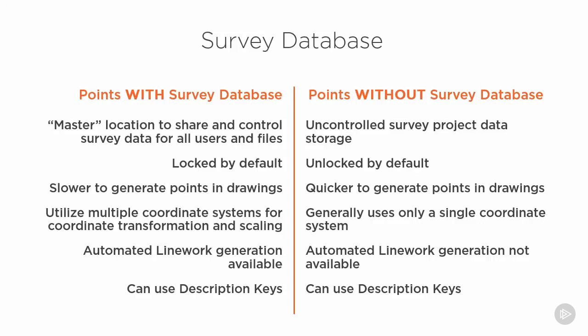Now we were able to use the description keys for either way. We'll talk about description keys a little bit more later, but that was that manhole symbol that did come in as a manhole, whether it was imported with the database or without. So let's end it there, and when we come back, we'll talk about survey figures.